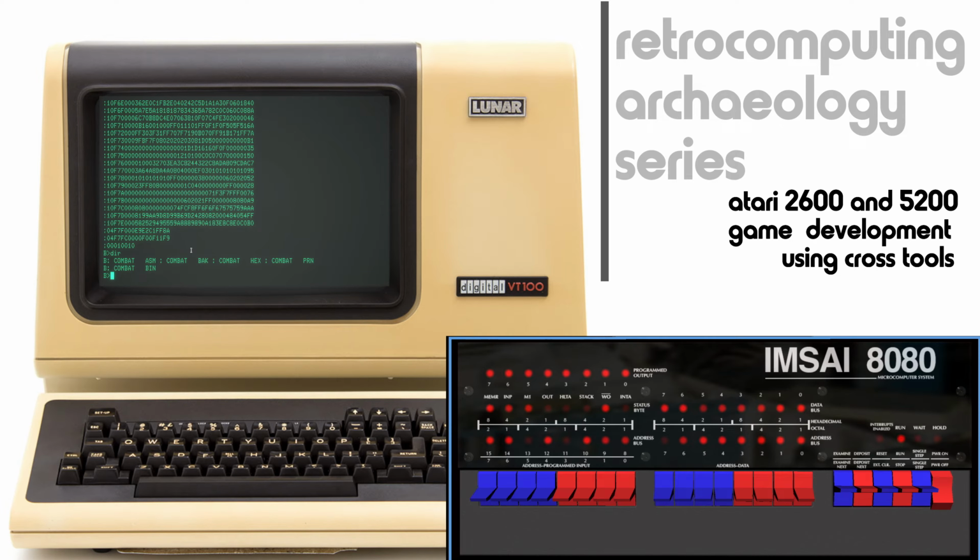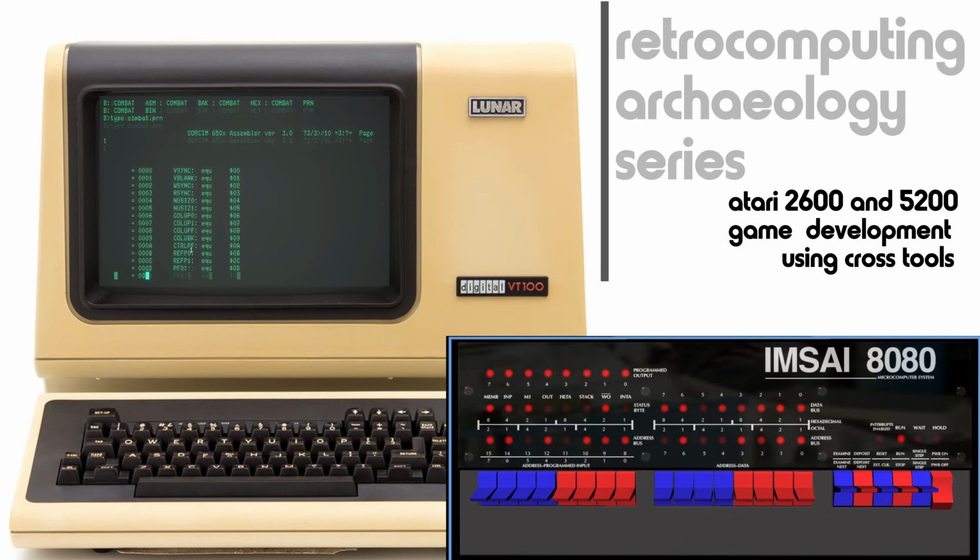We still need to turn that into something we can use, but I'll also show you here that we also got, as part of the process here, a listing. The listing contains virtually an output of every single line of the source file as it was interpreted by the assembler. In this case right here, we have a set of equates which assign labels to various registers inside the 2600 for the TIA and the Riot chips. And then finally, we get labels for each and every location in memory.